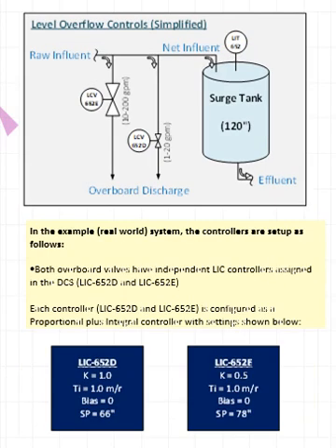So in the real world application, the system was set up with two control loops, and the settings were shown. As you look at that, you can tell they both have proportional and integral action. No derivative here, but there is integral action on both of them. And they both have two distinct different set points. You'll probably notice that those numbers are kind of the middle of the range that was spelled out in the functional description. We'll talk about that later.